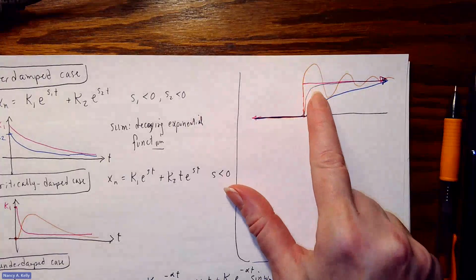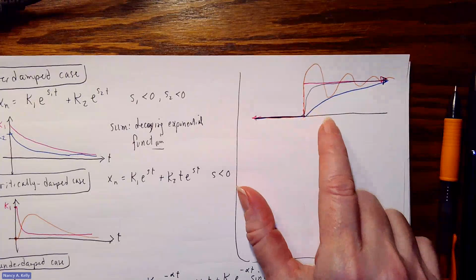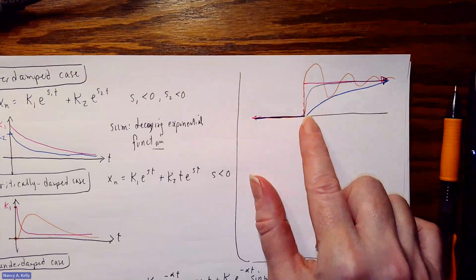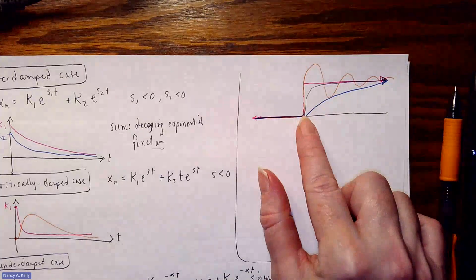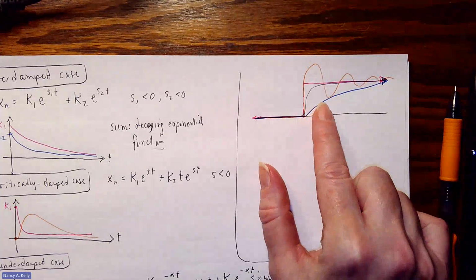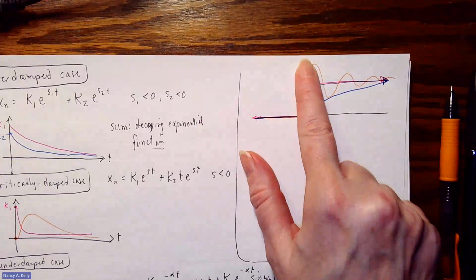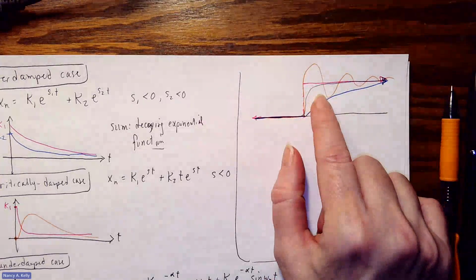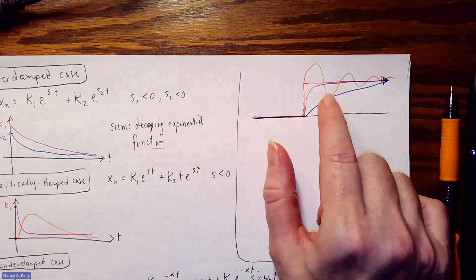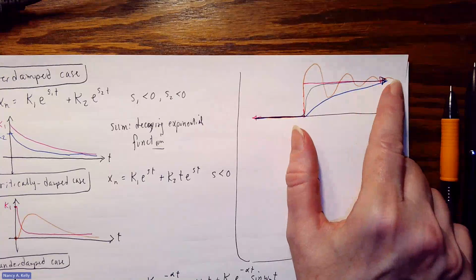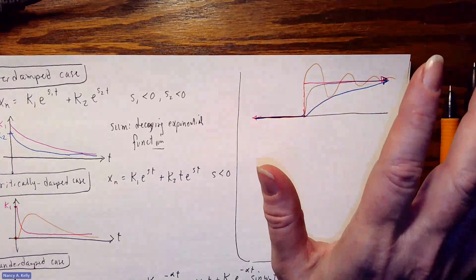So there are trade-offs involved in these responses. When you design a system, maybe you have to ensure that it doesn't overshoot, whatever the system is. Okay. And you say, okay, well, in that case, to really make sure that it doesn't overshoot, I better make it overdamped. Or maybe you need a quick response time, in which case you're going to let it overshoot, and that's okay. So having it go up like this is fine, right? Because speed is the thing that matters. And if you overshoot, it's okay. You'll settle down and get into the steady state that you need over here. Okay. And then, or maybe critically damped, depending on how you do the design.